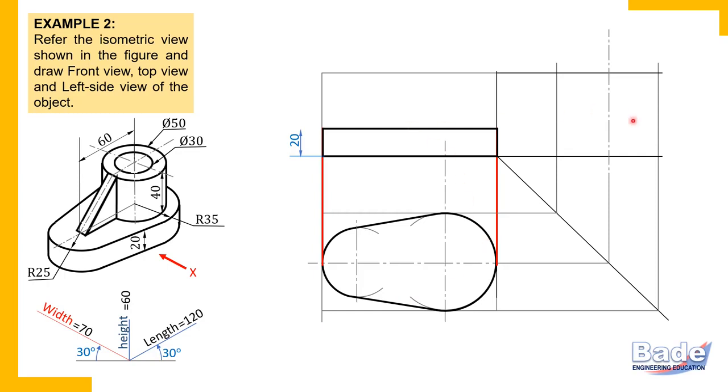In top view shape, the remaining two views are rectangles. Now let's complete the view of this plate in the side view. We already know it is simply a rectangle. A plate, if it is say a hexagonal plate or circular plate, shows its shape in one view. In the remaining views, it appears simply as a strip, a rectangular strip. So this shape in the top view, in front view it is a strip, a rectangle. In the side view also you will get that rectangle.